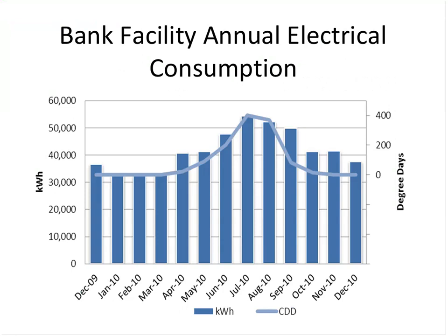This is essentially an office-type facility, and you would think that the cooling peak would be a more dominant part of the electrical consumption. So they're using almost 35,000 kilowatt hours per month, irrespective of the weather. So we immediately say, well, this building might have some issues, maybe lighting, inefficient lighting, interior, exterior, some equipment in there that's running all the time. So it gives you an idea of maybe what you need to look at in this building.